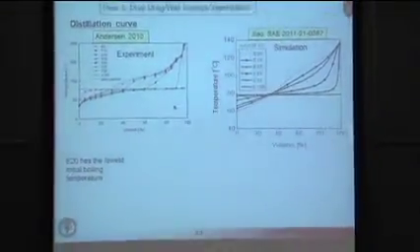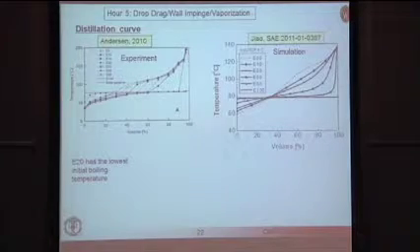And it has an effect when you come to look at the distillation curves. So this is for various ethanol gasoline mixtures. The dotted line here, this is an experiment, is the base gasoline. And here you're seeing different amounts of ethanol going from 5% to 100% ethanol. Looking at the experimental data, if we pick one of them, let's say the 25% ethanol content, you see you reach about 60% distilled before you see this rapid rise, and then it follows the gasoline curve.